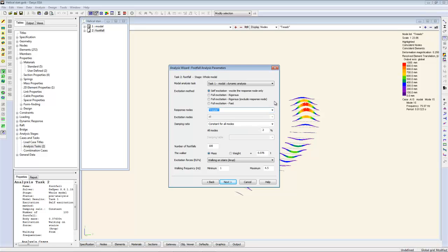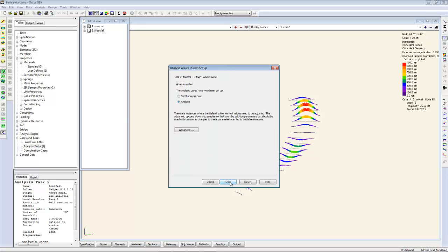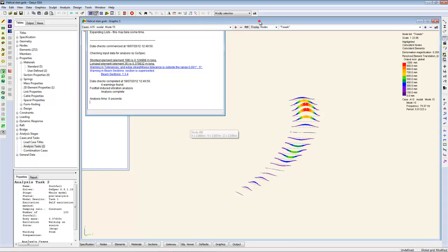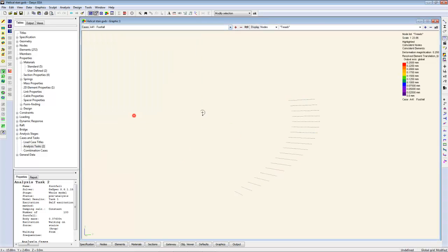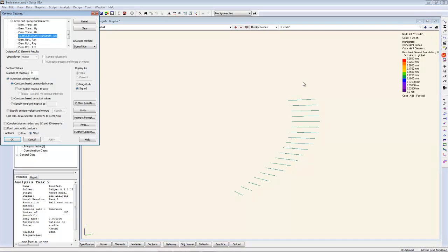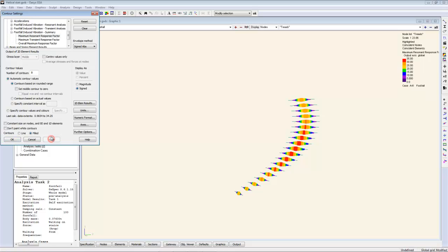People don't walk up and down the handrail. They're not interested in the vibration of the handrail. And so we're getting a response factor of about 35 on this staircase, which you can see is quite a lot higher than the floor plate, but probably still acceptable.